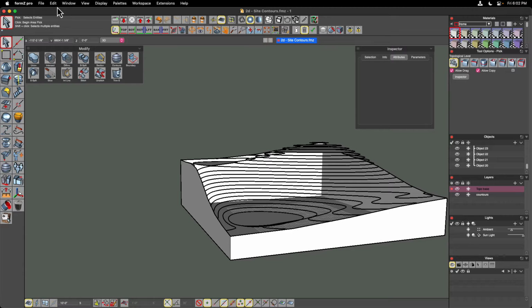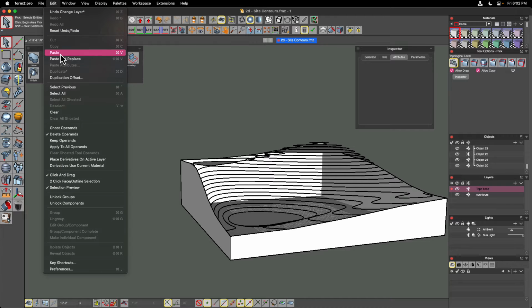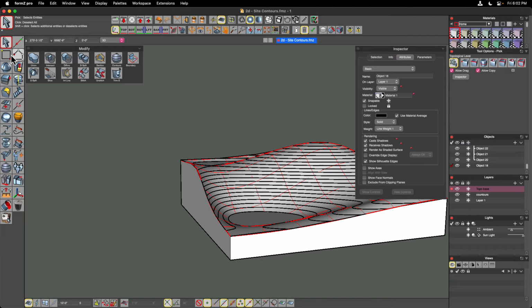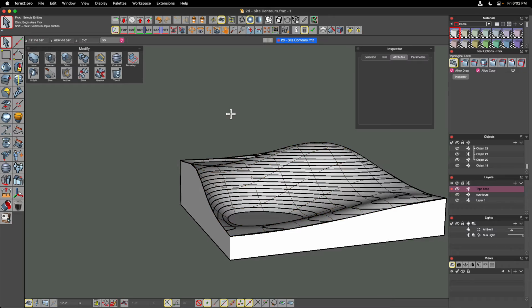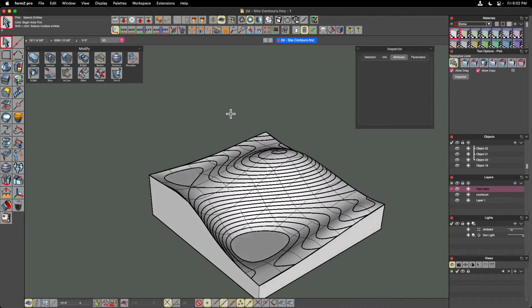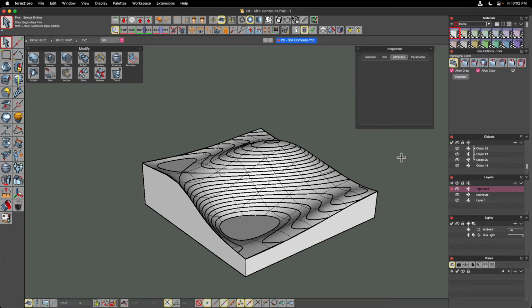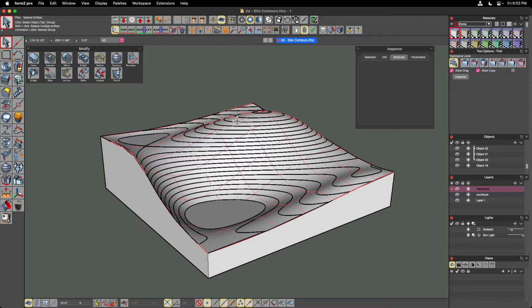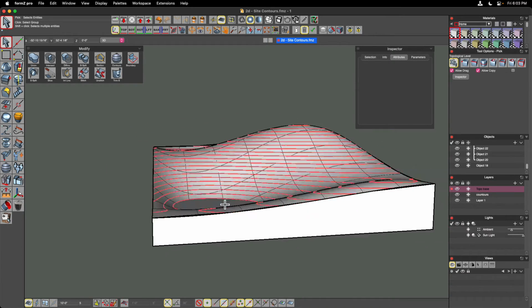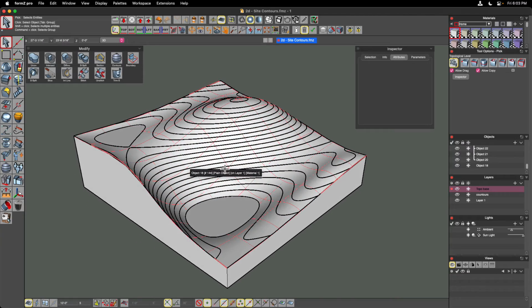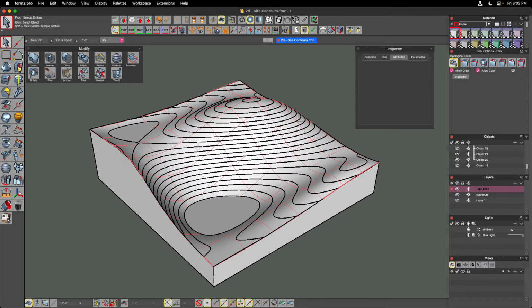And the next step is to simply paste my smooth surface right back into the file. So we can see now that I have an actual contour model with the elevation contours, which can be really helpful for visualizing where the objects that sit on this contour land in regards to height above the base of the model. This is a great way to kind of read graphically where things are.